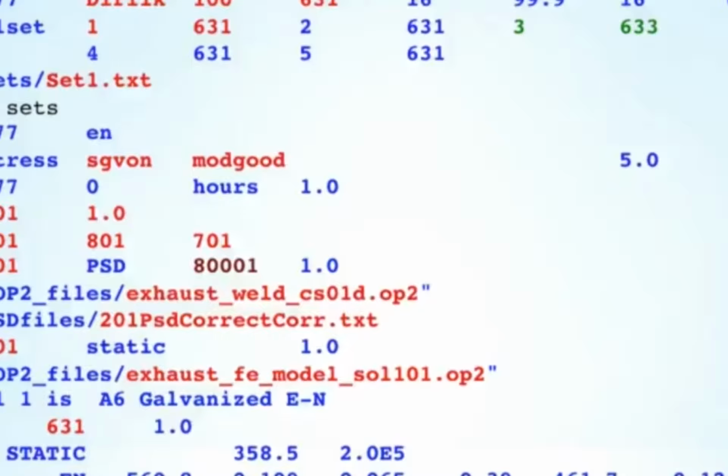We're going to read Nastran results, but if you repeat this with OptiStruct, you need to change Nastran to OS for OptiStruct. I've requested corner results, but more typically you would request center results there. By requesting center results, your analysis size probably reduces by about 5 to 10, depending on what kind of elements you have. And then the next item there, naught, is log level. That defines how much output you write at each output point. It can either be 0, 1, or 2.